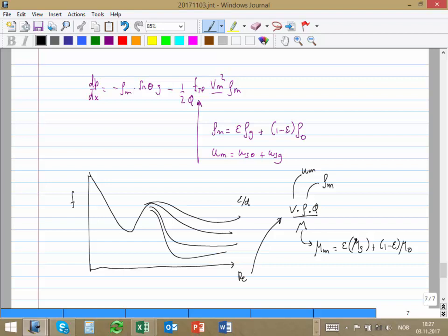Okay, and here comes a bit tricky, and this is where different models differ a bit. Some people say it's not like that, but I have to take into account which phase is the wetting phase and the flow pattern. They say that's not correct because it's not like in the tubing we have one part covered with liquid, one part covered with gas. Actually, if it's annular flow, we might have everything covered just by liquid. But if you have any other kind of flow, that's where the difference comes from. But we are going to use this simple model, this drift flux approach.